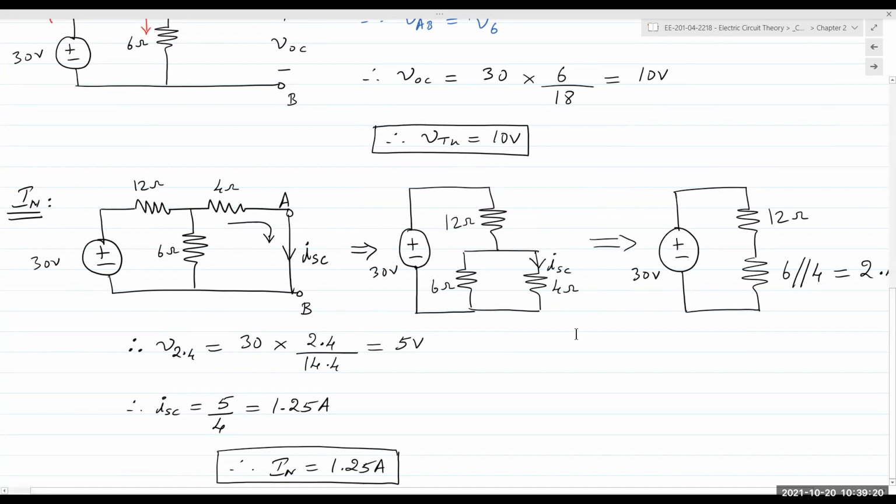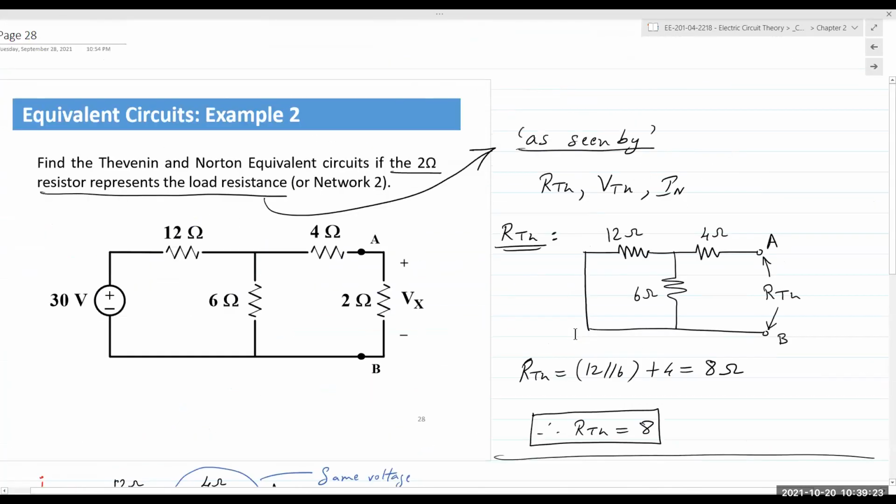So if you go here, and it simply tells you, find the Thevenin circuit between the terminals A and B, then your 2 ohm resistor is part of your analysis. All 3 circuits. Does that make sense to everyone? Right? If the question simply states, find it between these terminals, then no modification necessary. You automatically begin your analysis between those terminals.